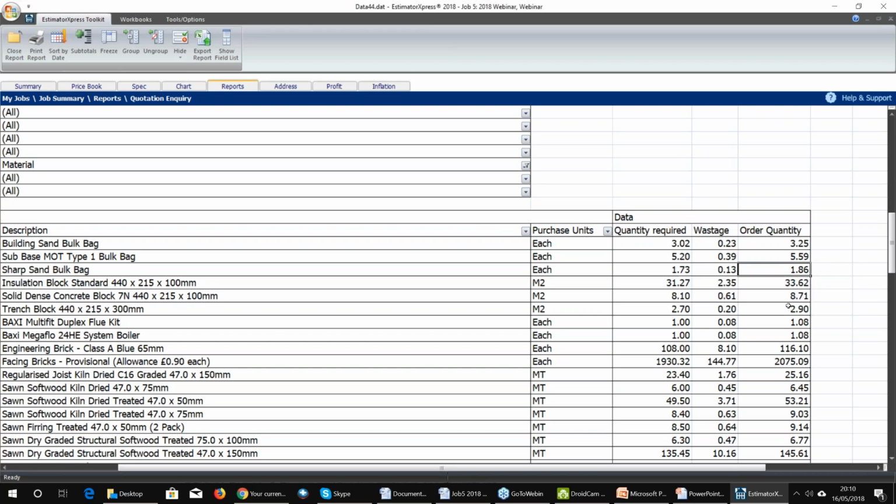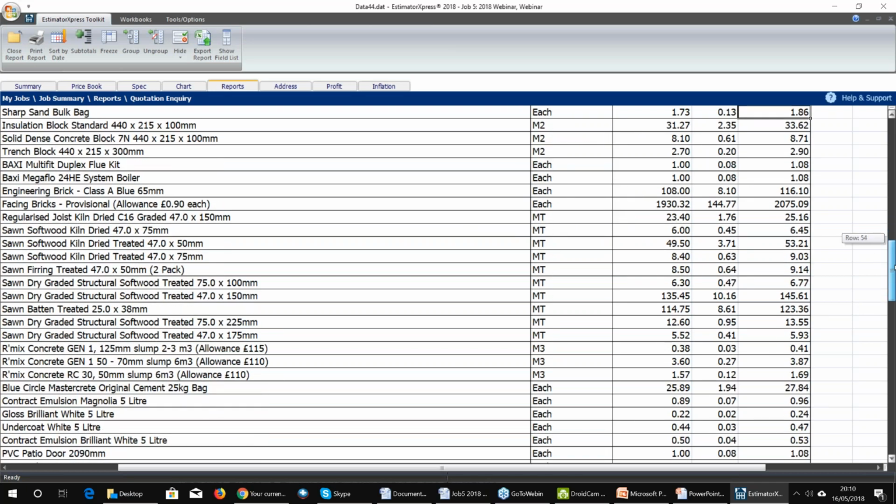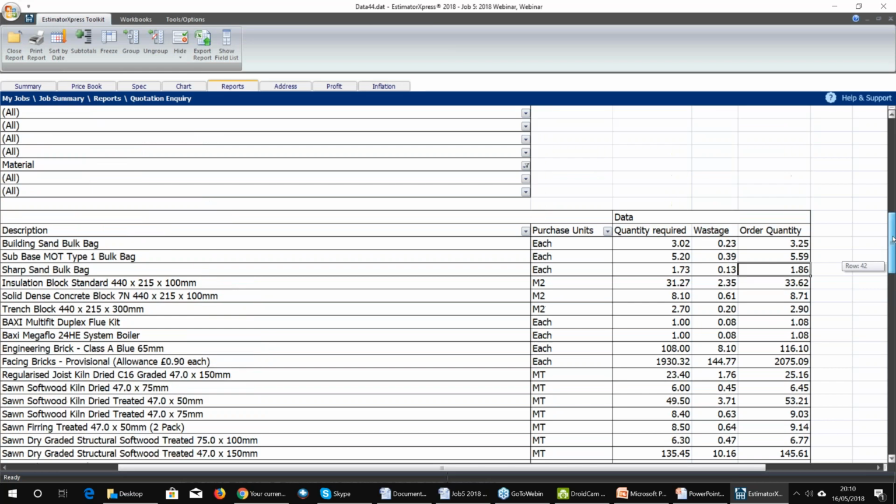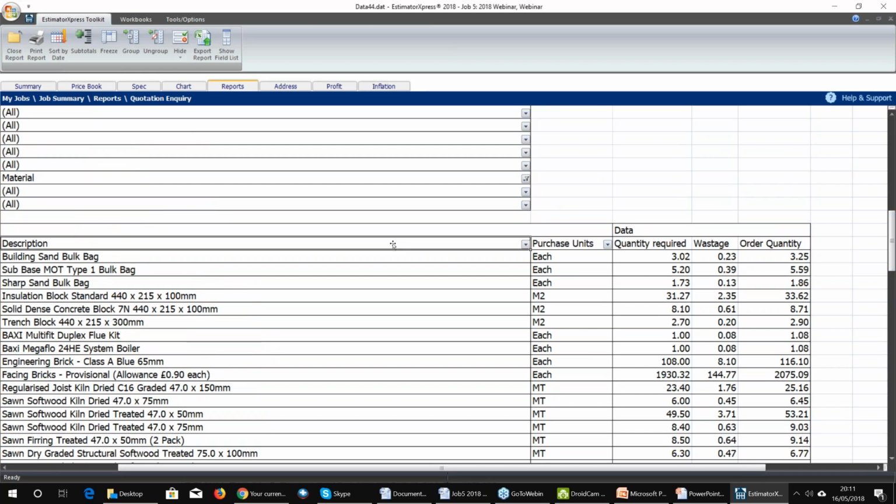Almost 2. So where some of the figures go over, it counts towards some of the figures that are just a little bit shy. There isn't a button within the software to round them up. It does presume that you might have materials left over for the next job, especially things like timbers, bricks, tiles, and such like that. There was a bit of a hacky way to round stuff up, but it's not something that generally does what it does anymore, because the features for it have been supplanted for our estimating service stuff.